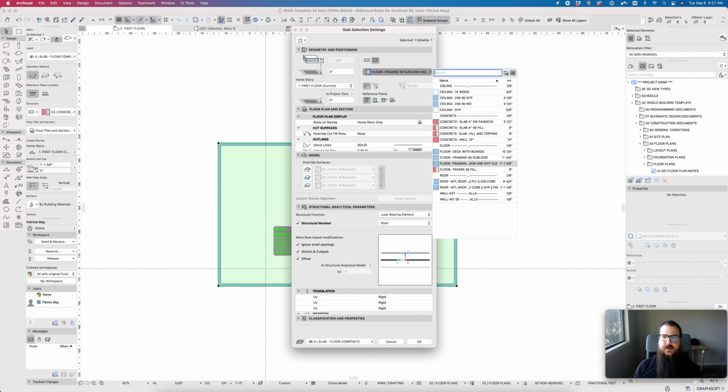It's important to note that the tool that you're using, the name of that tool, i.e. slab tool, wall tool, beam tool, column tool, is not restricted to just modeling those elements. That's the name of the tool, but they can be used to model any number of things. For example, the roof tool is great for modeling sloped garage slabs, sloped porches and patios and decks, sloped ceilings and shower pans and things like that can all be modeled with the roof tool. The slab tool is always parallel and horizontal surfaces on its extrusion for its reference plane.